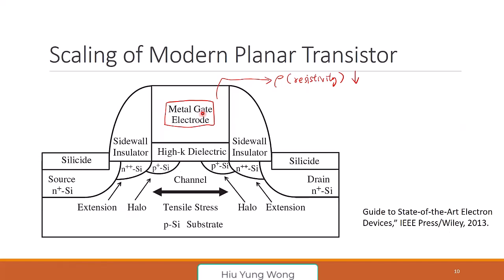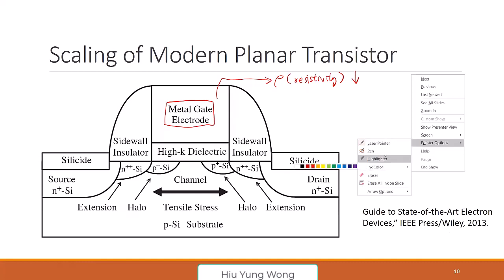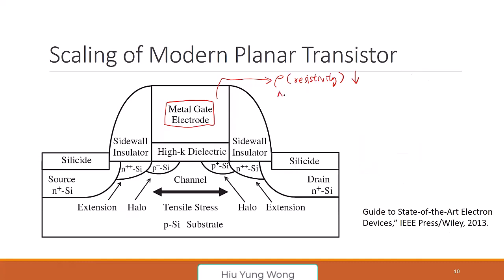There's another reason, so-called poly-depletion. I won't go into detail, since they are not here now, so maybe it's okay, no poly-depletion. You will see this if you use power device. Basically, when you turn it on, you're going to form a depletion layer at the bottom. And because it's depleted, then you actually have a thicker gate or equivalent gate oxide, right? So just know that you have this. Otherwise, not that important. I mean, it's important, but we don't see it much now.